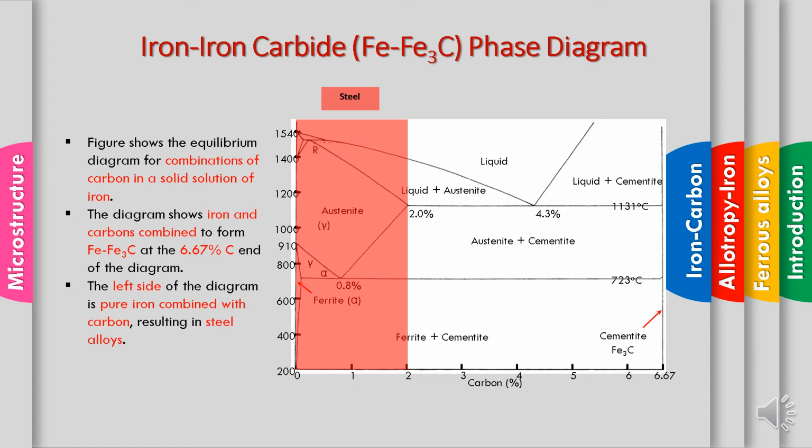And then for the mixture of up to 2%, basically from 0 to 2% of carbon, there is the region of steel. Along the region we can analyze several lines, including the line at 0.8, the line before 0.5 or so, and the line here, to see what will happen to the microstructure. And the rest is the cast iron region, from 2.0 above to 6.67% of carbon.